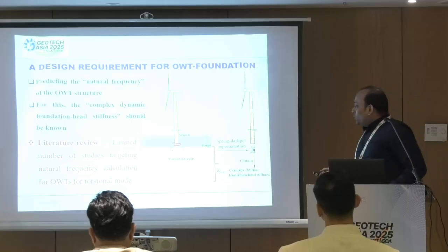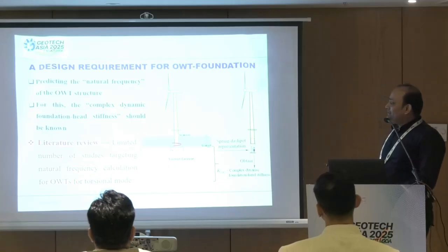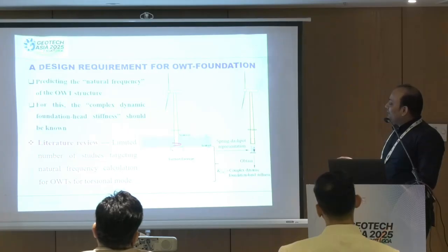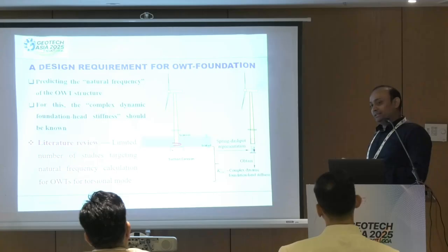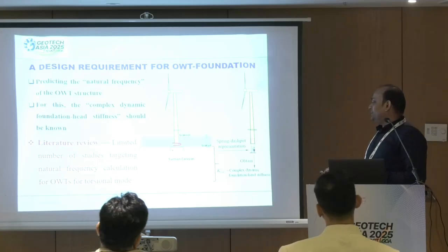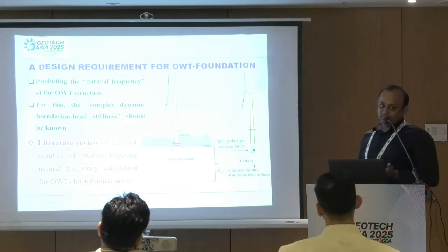So basically, this caisson and soil can be modeled as a spring-dashpot system, which is nothing but a complex dynamic foundation head stiffness at this particular level.